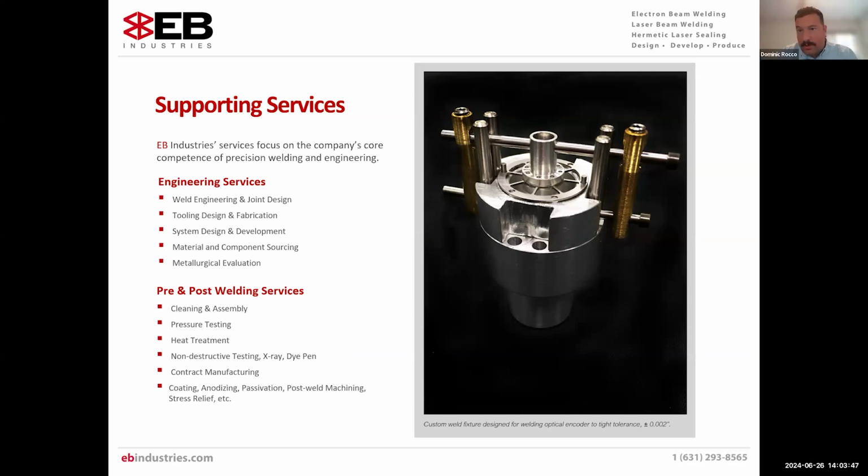See another question here. What is the minimum number of parts where E-beam welding becomes competitive with TIG, thinking of prototype quantities? This is a really good question because this does pop up when new projects arrive and we talk about what kind of initial investment is worthwhile. So I think the best way I can answer this is TIG does have its advantage in a way where it's a manual welding process, whereas they can access and maneuver assemblies a little bit quicker and easier than we can because EB welding takes place in the vacuum chamber.